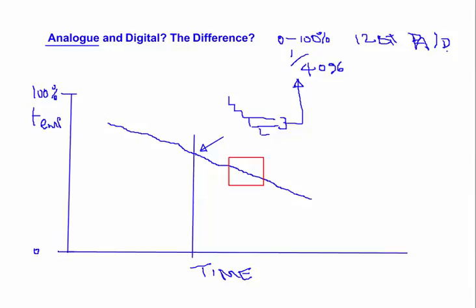And I say that because if the analog signal moves within that resolution, that is in fact a deadband which is present by virtue of the fact that we have digitized an analog signal that's been captured.